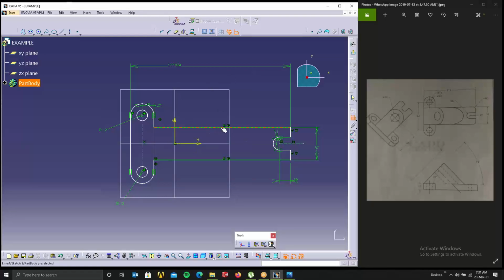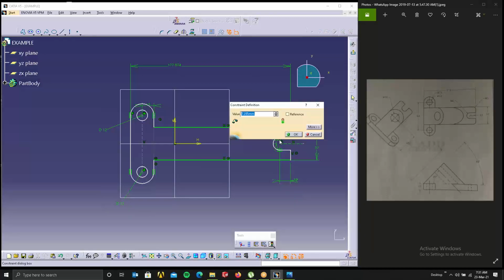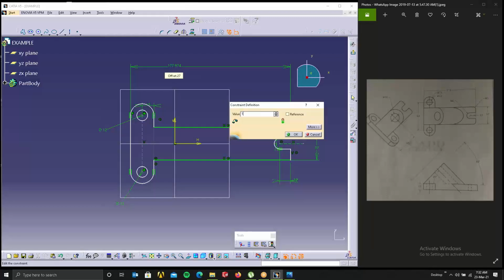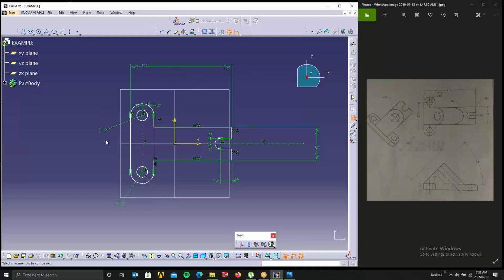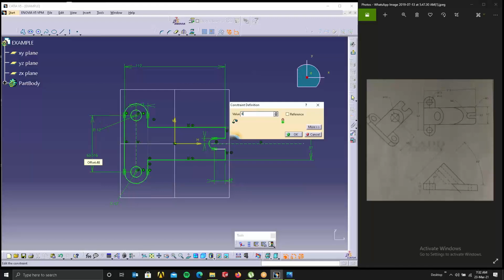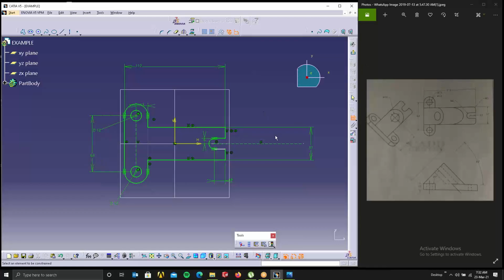And what else do we have? Here this one is 6 radius. This is 12. This and this, right click, allow symmetry line, so the vertical. Okay. Now what else? Distance 63 they have given here, this to this 63. Anything else left out? 6, 12, 37.